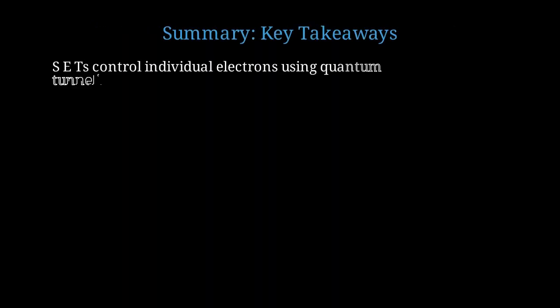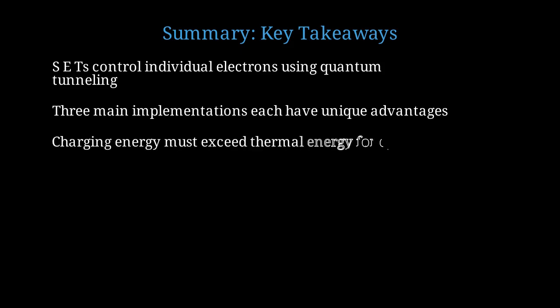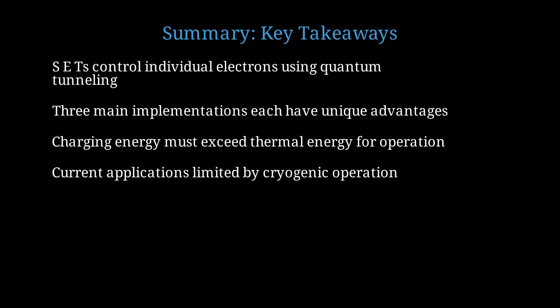Single electron transistors are nanoscale devices that control individual electrons through quantum mechanical tunneling and the Coulomb blockade effect. The three main implementations, quantum dots, nanowires, and nanomembranes, each offer unique advantages for different applications. The fundamental requirement for operation is that the charging energy EC must significantly exceed the thermal energy kBT. Current applications are limited by the need for cryogenic temperatures, though research continues toward room temperature devices.